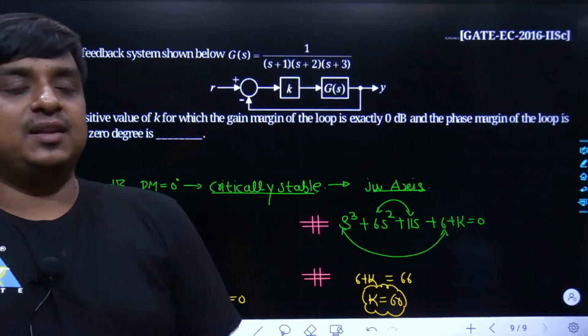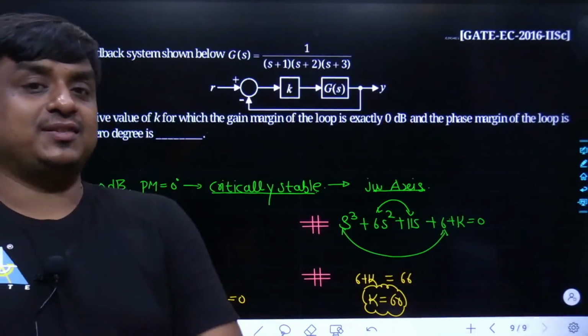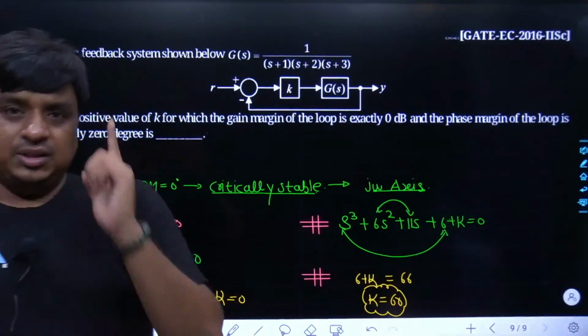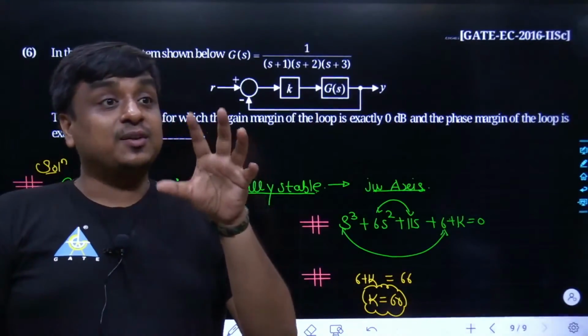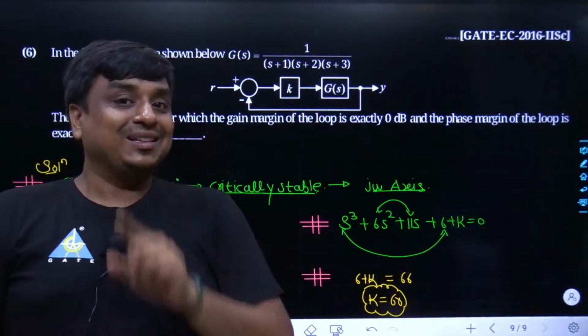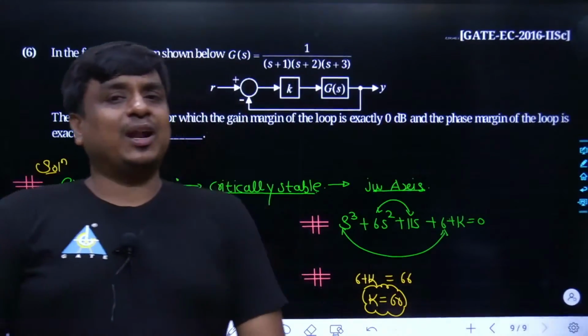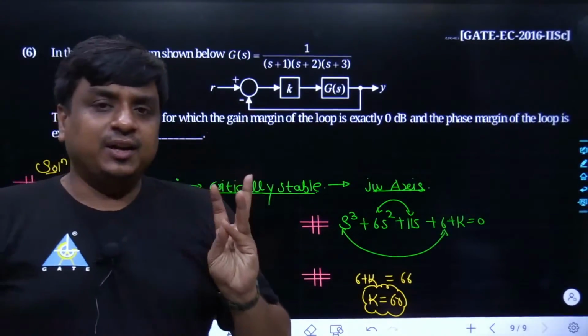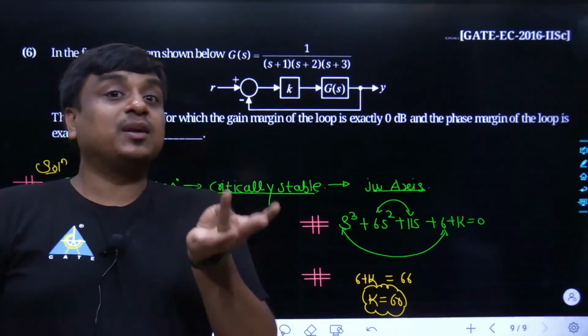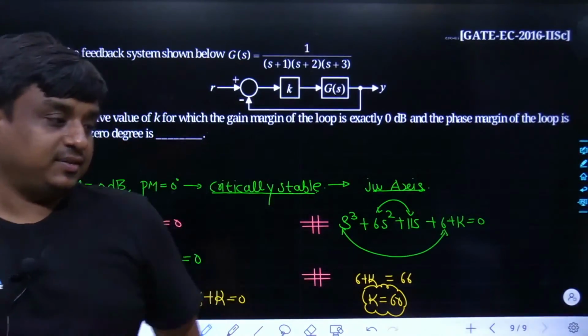Anyway, in a lump sum I can say, whenever a pole is introduced into the system, stability always decreases. Whenever zeros are introduced towards the left-hand side of all the zeros as well as poles, the system stability increases. So if poles increase, system stability always decreases. If zeros increase, sometimes it increases, sometimes it decreases.